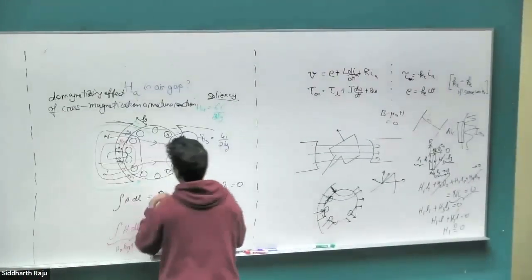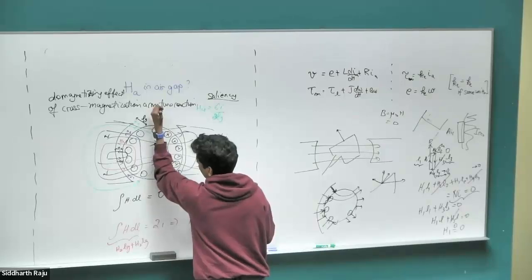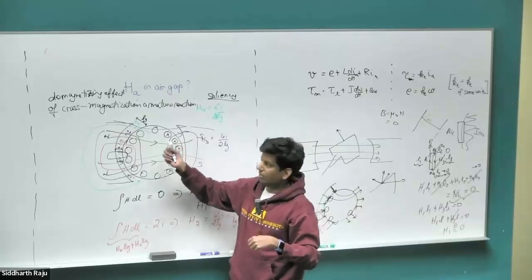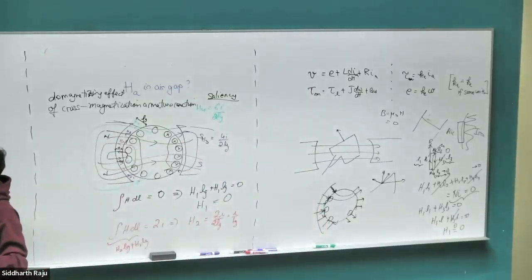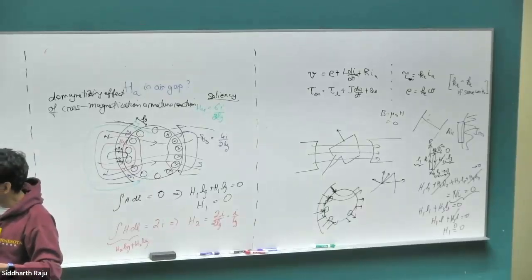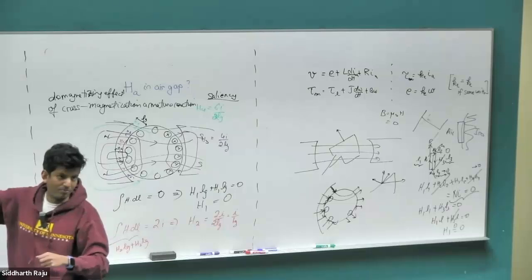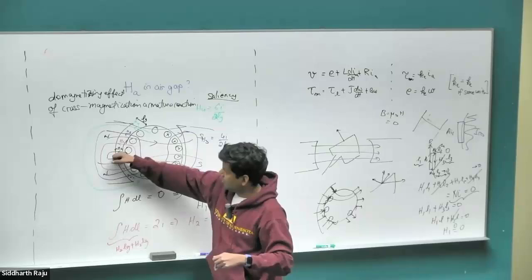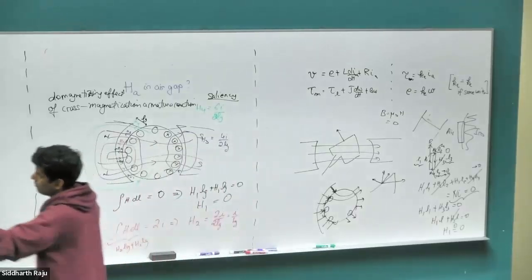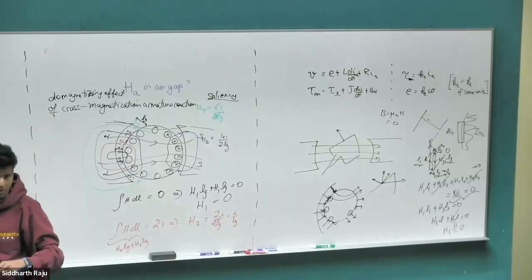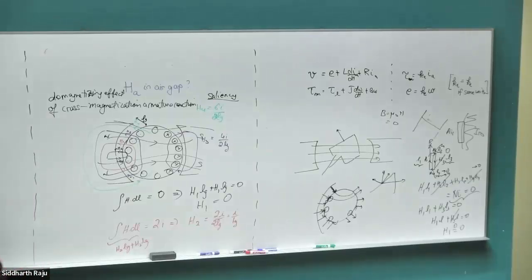So due to the external magnetic field, the B would have been the least at this particular 90-degree point. Right? Because that's where it flips going from the north to the south. If you look at this diagram here, B goes from north to the south at that 90-degree angle. But that's when the magnetic field due to the armature current is its maximum. So when it's at 0 degree, the B field due to the magnet, if you do the Fourier components for this, the maximum would be at this point. But that's when the armature component becomes 0. Right? They are phase shifted. Any questions?